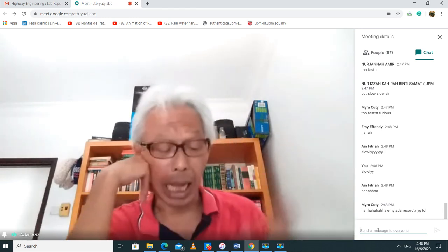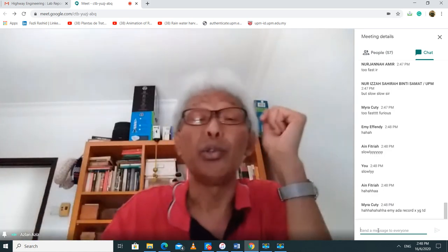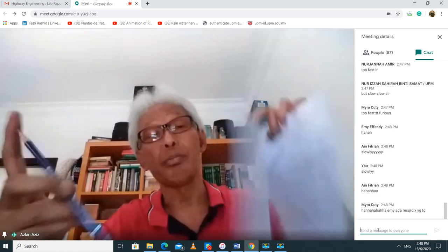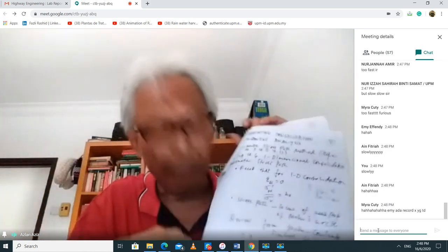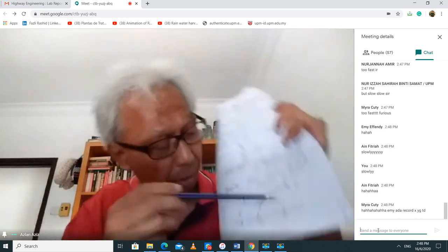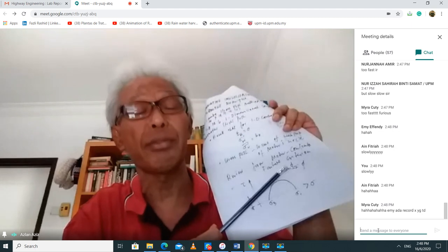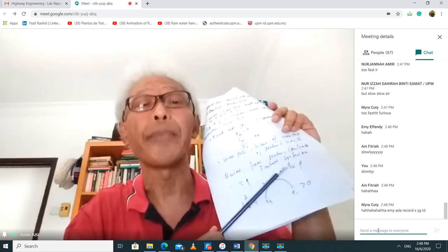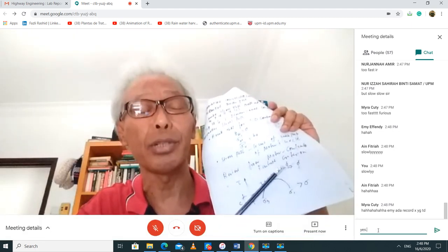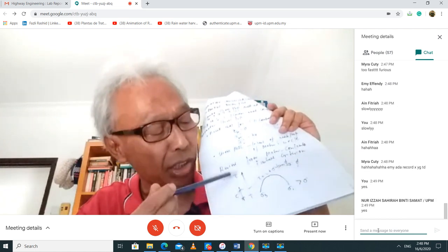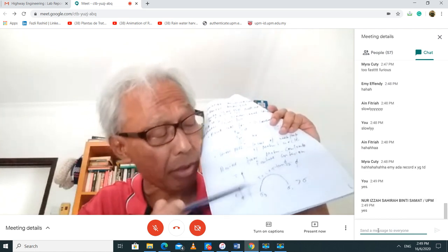Okay. Now, you know that when you draw this Mohr circle, this is an old thing, you know this, right? When you draw the Mohr circle, I can draw a line tangential to the Mohr circle. Yes or no? This is the shear stress that will cause failure.